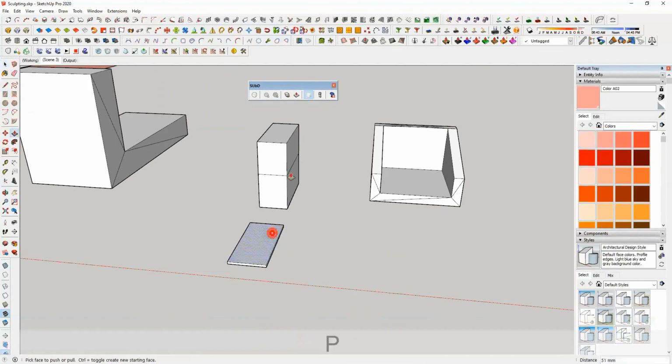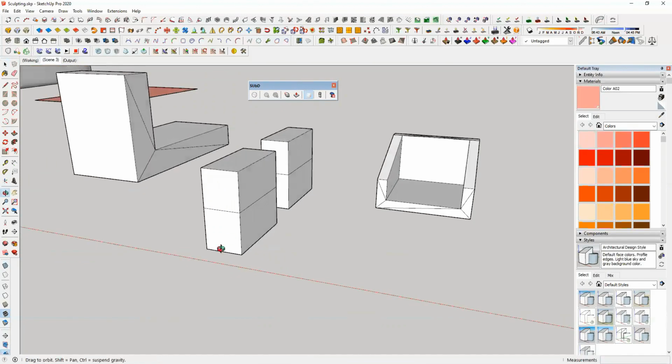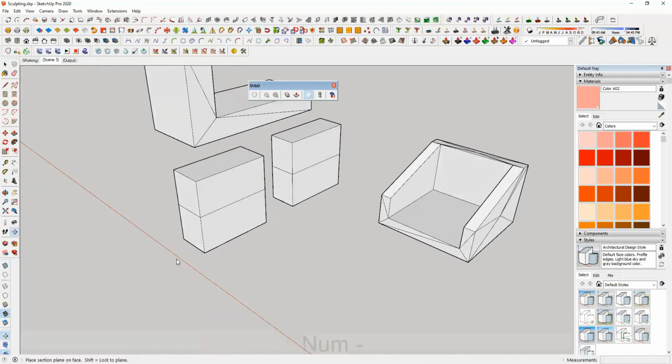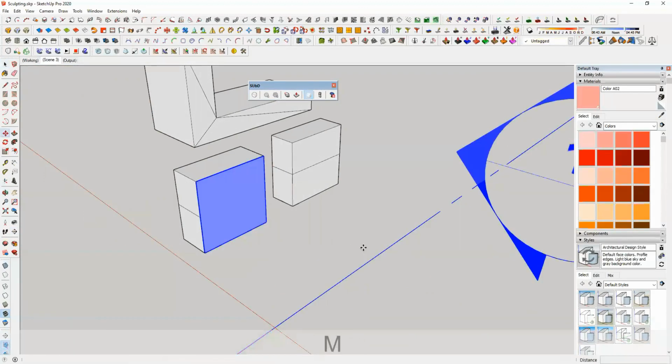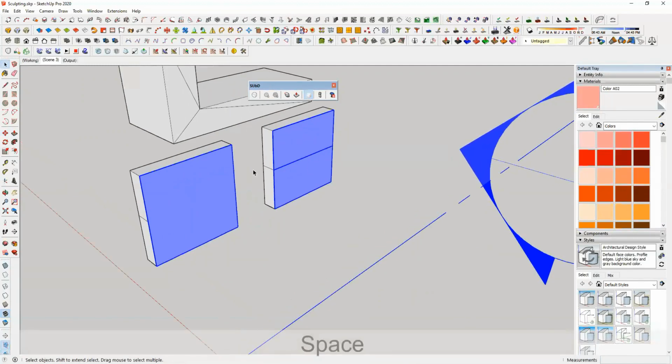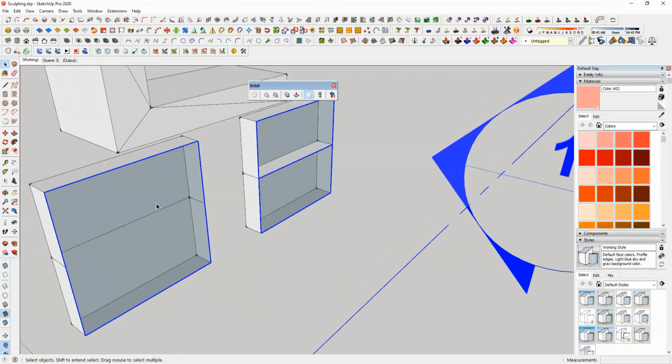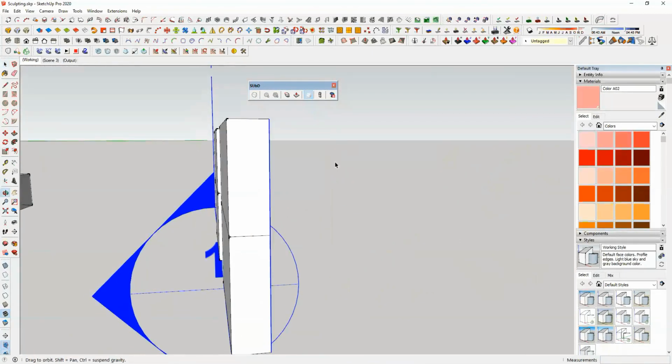Let's push pull this with the normal push pull this time, and from here I'm going to use this push pull, which is kind of the copy push pull. But if we do the copy push pull, then the difference will be that if I cut a section, then there is no face in between, right? So if I go to working, you can see that we have a face in case of our SketchUp push pull, which is left out, and in this case we don't have the original face, only the edges at the corner.